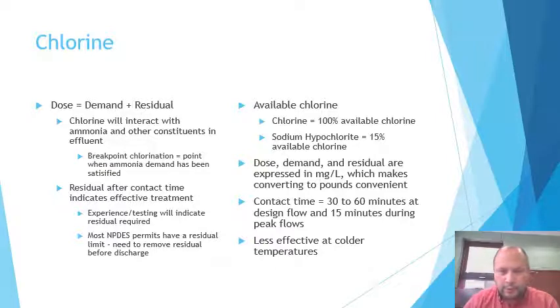So we'll go into a little bit more depth about chlorine. If you've done the math homework already, you've heard me say in doing the math problems, this equation, the dosage equals demand plus residual. Let me expand on that just a little bit. I don't think you're going to need to get into too much detail about the chemical reactions that occur with chlorine on a class 1 exam.